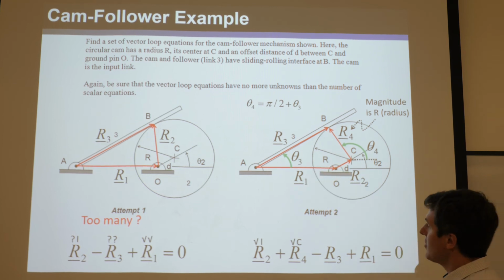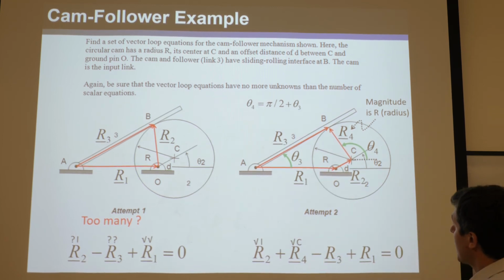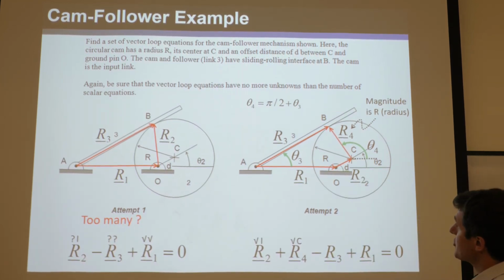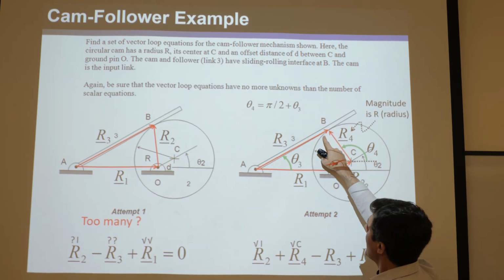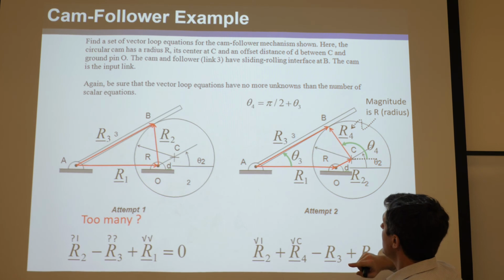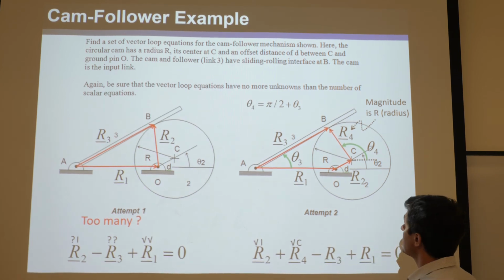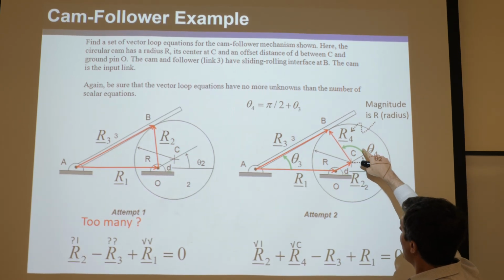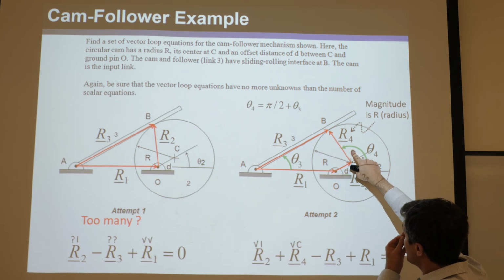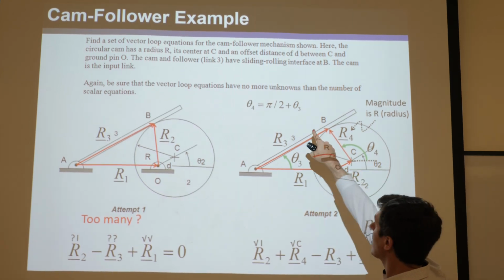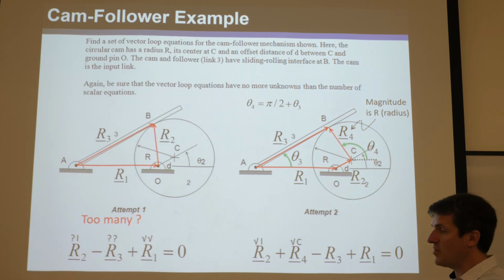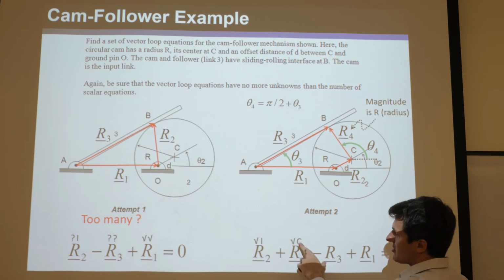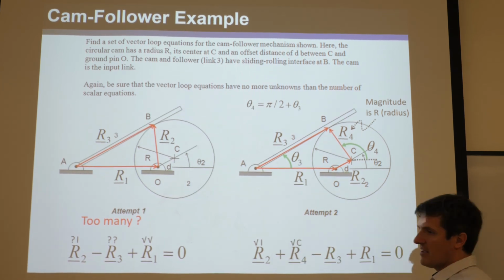Okay? So here is the first time we're using the C, the constraint thing. Okay? So remember, here's theta 3. Okay? Here's theta 4. And it's constrained because we know this will always be 90 degrees or pi over 2 radians. Okay? No matter what. If the circle touches that, it's always pi over 2. So you can know if this is theta 3, so from the horizontal up to there is theta 3, plus pi over 2, this is always going to be a 90 degree angle, that will equal theta 4. So this is a new equation we're introducing. You could either think of it as, we don't know this, but we're going to introduce a third new equation, or it's just constrained, and here is the equation. Okay? So this is just how this works.